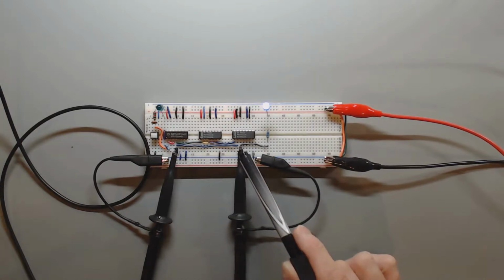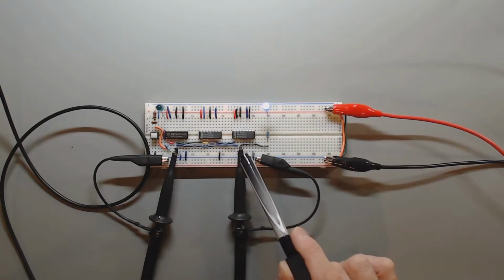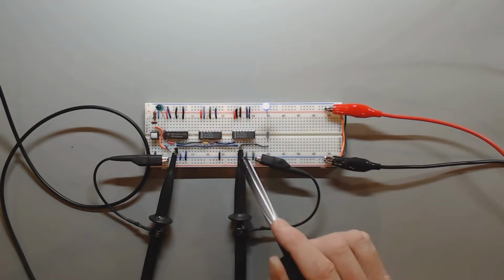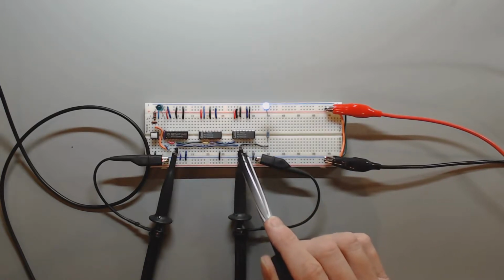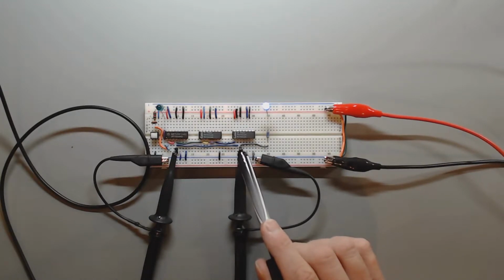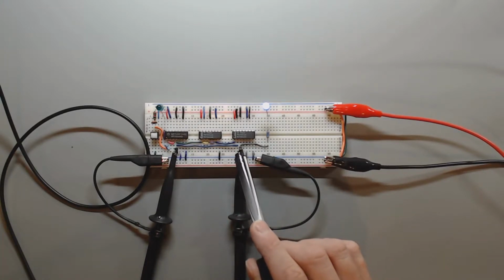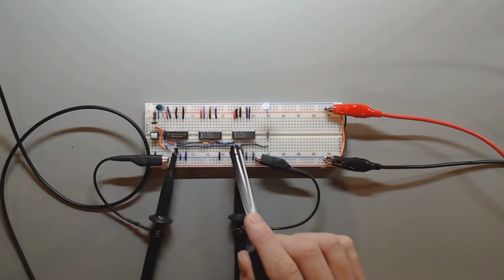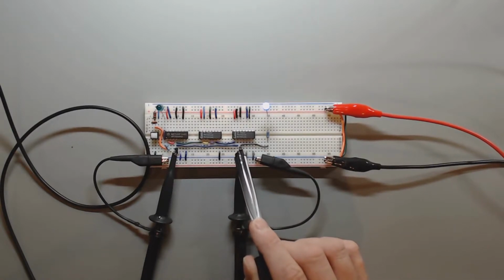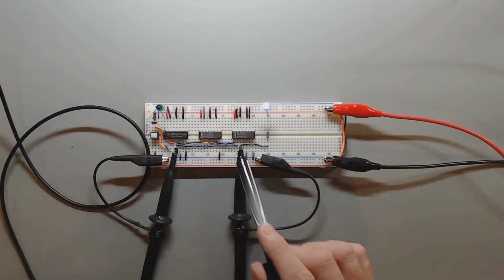And what we're going to do is have the oscilloscope trigger on a high to low transition on this signal, meaning we want to capture the state of the voltages in the circuit at the point where this output becomes low. And again, because there is a glitch, the combinational logic implemented by the circuit really should never be producing a low output here, but we will see that it actually does. All right, so let's give it a try.